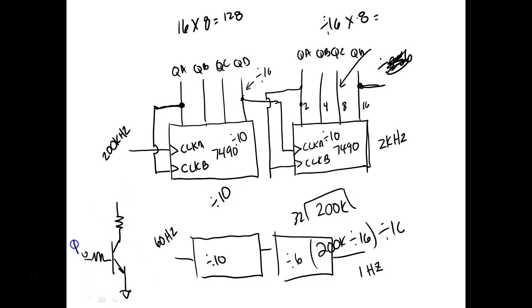So if we design this right, I could bring this in on this side, and over here I'd be getting this out. This would be at 60 hertz. I could divide by 60. Then I can bring that into regular BCD counters, and I can make a digital clock, because that Alabama Power 60 hertz is very, very accurate.